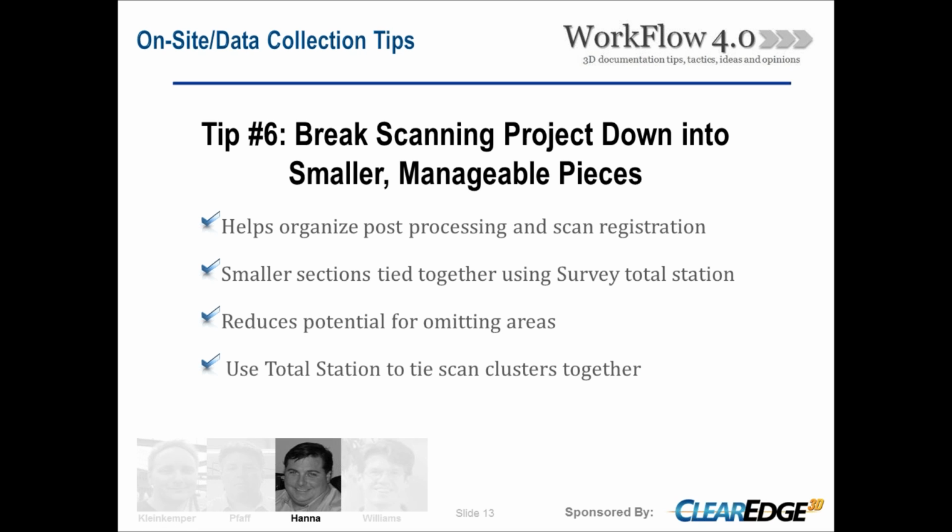Tip number 6, we're often tasked with doing rather large projects, and in particular when you're scanning the MEP up in ceilings, it can get quite a bit overwhelming, especially for the scan crews and then the post-processing of the data and the registration down the field. So as both Mike and Larry have pointed out, it's absolutely essential that we use survey total stations with all our scanning projects to aid us in the post-registration process, as well as it really enables us to break a building down, for instance, into smaller chunks that are much more manageable.